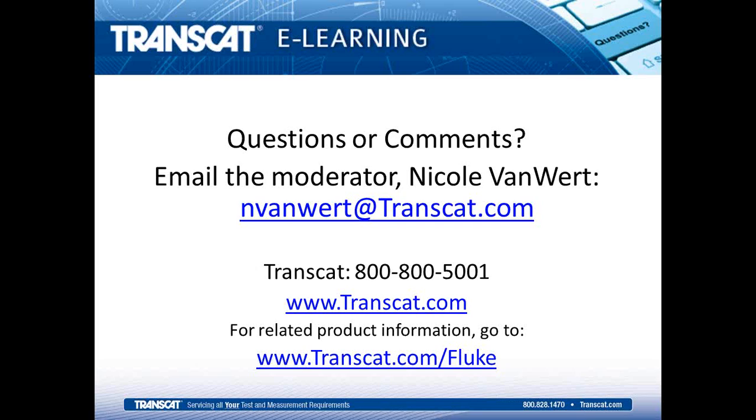Okay. Is it advisable to use the ITS-90 table along with the dry block and RTD ohm reader with no reference probe? Yeah, read that one more time if you would. Is it advisable to use the ITS-90 table along with the dry block and RTD ohm reader with no reference probe? Okay, I think I know what we're getting at here. So the concept would be I have an RTD in the dry block and I'm measuring the resistance of it and then pulling that off of a chart of some sort.